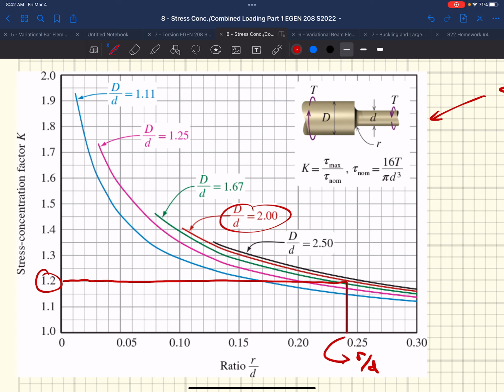How often in field applications would you hit those curves on the mark? Are you always going to get 2 and 2.5, or would you get an estimate? It all depends on what the actual element is used for in service, right? If you're really stepping down the shaft, then you're going to get higher and higher, right? And this graph is only good to 2.5. You could only reduce it by 2.5. So you would go to some other prepackaged solution, or you step it even further.